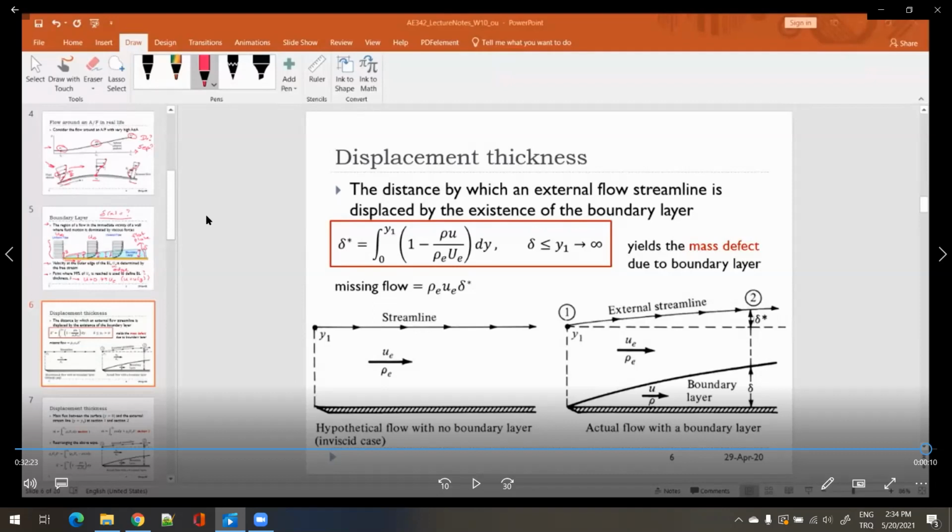The Mach number will be locally supersonic in some regions, and locally subsonic in some regions. And there could probably be a normal shock wave somewhere downstream of the supersonic pocket. So all those physics will be there. On top of that, there will be a boundary layer. There will be an existing boundary layer, and for example, we define this thing called edge velocity, right? The edge velocity corresponds to these Mach number changes we discuss in the sense of inviscid flows.